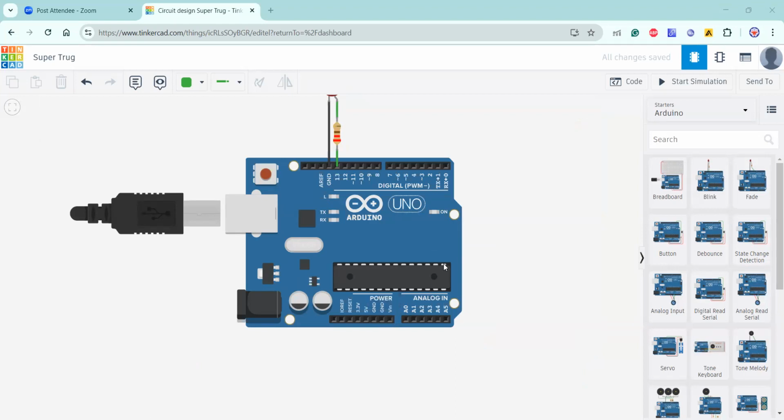The minimum voltage required to turn on Arduino is 5 volts, and the maximum can go to 12 or 24 volts based upon the manufacturer of the board. The same USB connector can be connected to your laptop or PC, or directly to a mobile charging adapter plugged into your socket. For the DC jack also, we choose the same rated adapters like 5 volts 1 amp or 5 volts 2 amps, ranging from 5 volts to 24 volts.